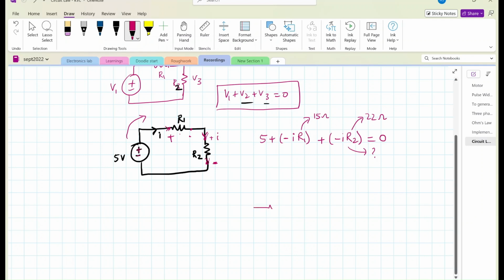Suppose I have a circuit, and I just pick up some part of it where it says it is 2 volts here. I don't know what is the voltage over here, Vx I don't know, but I know it is a 100 ohm resistor here, a 20 ohm resistor here, and a current of 1 ampere is flowing. So if I know these details, still I can apply this. Even if I don't know a lot of details about it, still I can apply KVL for even a segment of a circuit. How can we do it?